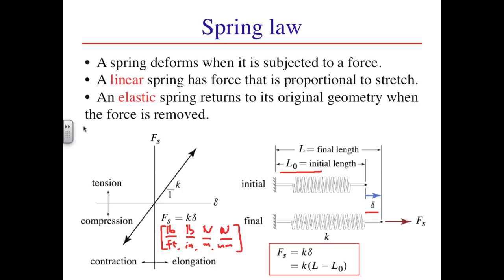If you disassemble such a pen and hold the spring between your fingers, you realize quickly that you can easily apply an excessive load that unravels the helical pitch of the spring and leaves it permanently deformed. This implies that our linear force-displacement relationship is just a model and is only expected to be valid up to some threshold force not shown in the figure.